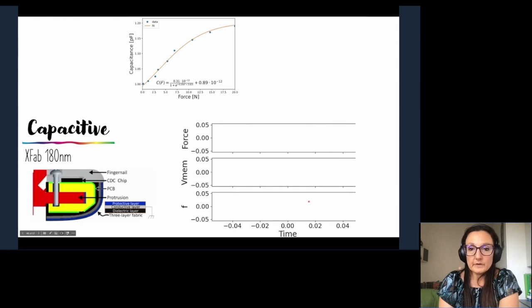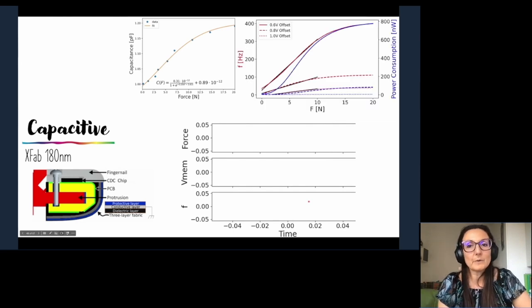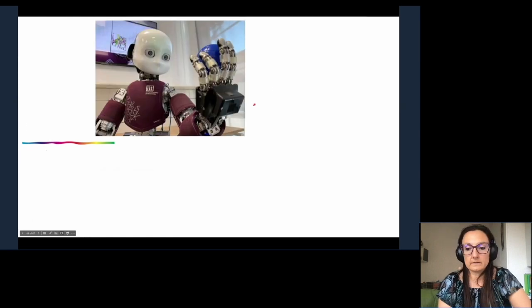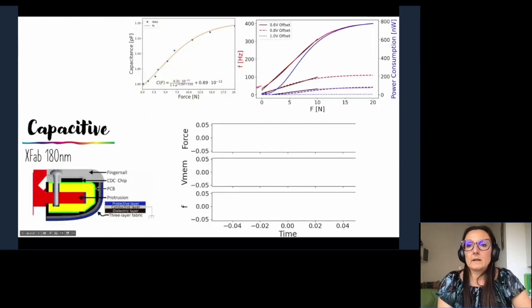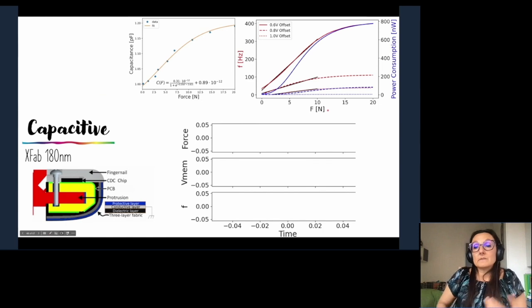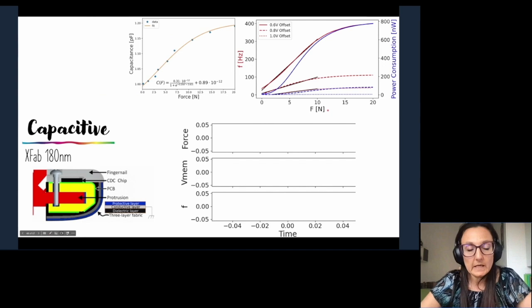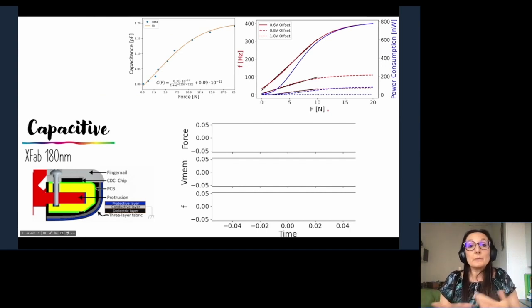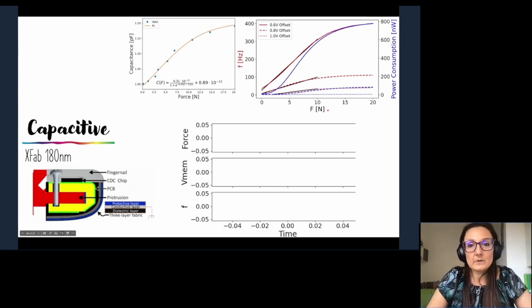So we also worked on the capacitive one. This is, again, a GIF that is not working, but basically what you can see here is that the output frequency correlates with the input pressure and not the slope this time. So you have sustained activity that is proportional to the input pressure, similarly to the slowly adaptive fibers. For this one, we have the chip back, but we still need to do the experiments, and we are in the process of doing so. So these are simulations of the circuit.